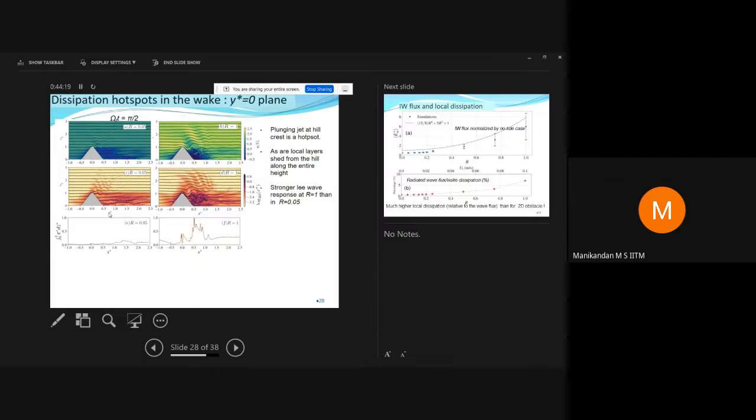So you have a so-called descending jet, and then you have these V waves. That is a spot of intense turbulence. But that's just at the top, right? The jet goes only so far. But at the bottom you also have strong strips of displacement. So the flow is separating out in strips that are of the order of U_C over N, that's the vertical density scale, and you get strong vertical shears in that region.